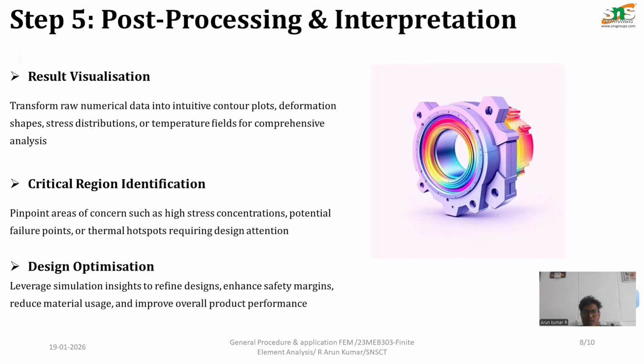The last step is post-processing. Result visualization transforms raw numerical data into informative contours, plots, deformation shapes, and stress distributions or temperature fields for comprehensive analysis. Critical region identification points out areas of concern such as high stress concentrations, potential failure points, and thermal hotspots that require design attention. Design optimization leverages the simulations to refine the design, enhance safety margins, reduce material usage, and improve overall product performance.